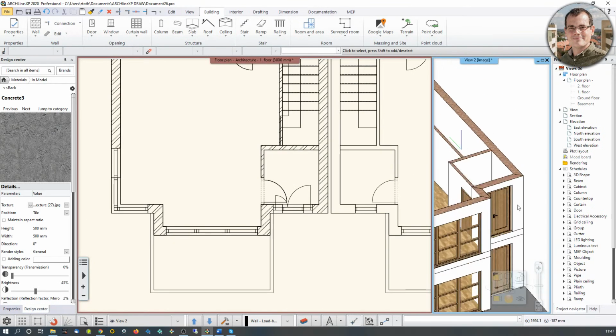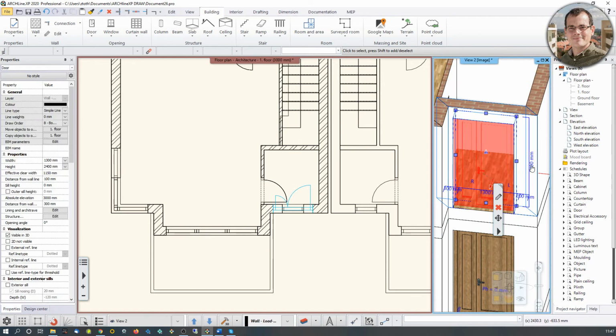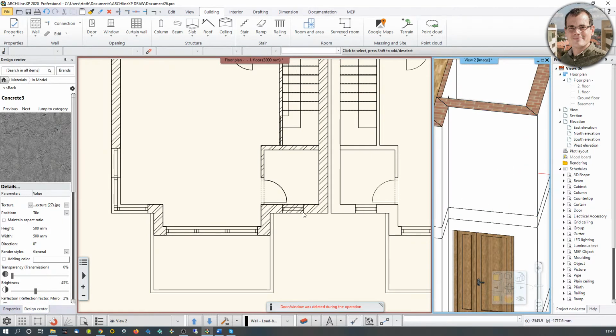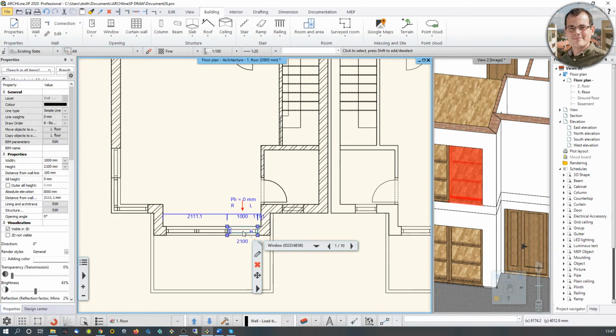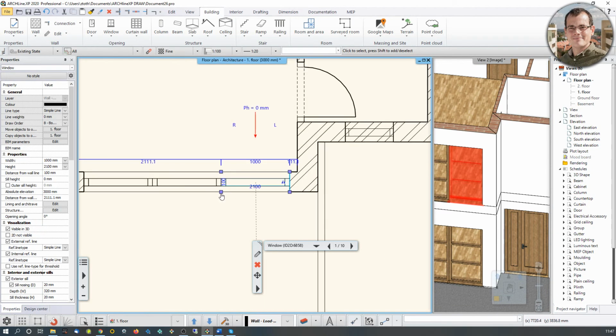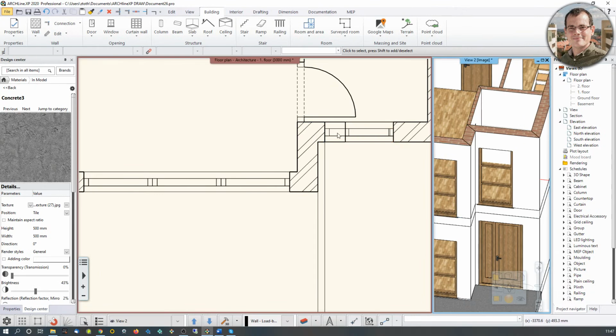Okay, another difference between the first and the second floor is that this should not be here. This should be instead a window, as we see on the drawing. So how do we create a window based on that? Now, it's not really easy because I see that this window has a different size than that one. So I'm just going to click on the window that I have, click on the node, move a copy, and I just copy paste this window on top of the other one.